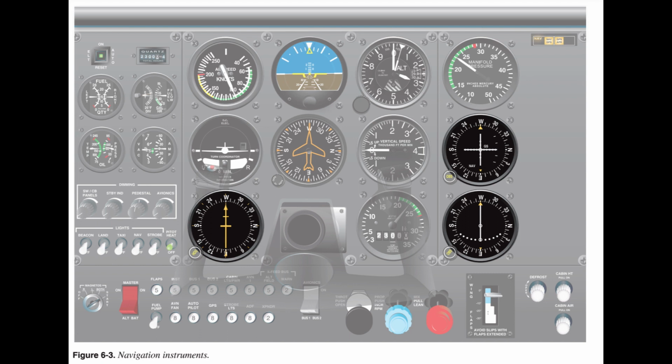Pitch control. Changing the pitch attitude of the miniature aircraft or fuselage by precise amounts in relation to the horizon makes pitch changes. These changes are measured in degrees, or fractions thereof, or bar widths, depending upon the type of attitude reference. The amount of deviation from the desired performance determines the magnitude of the correction. Bank control.